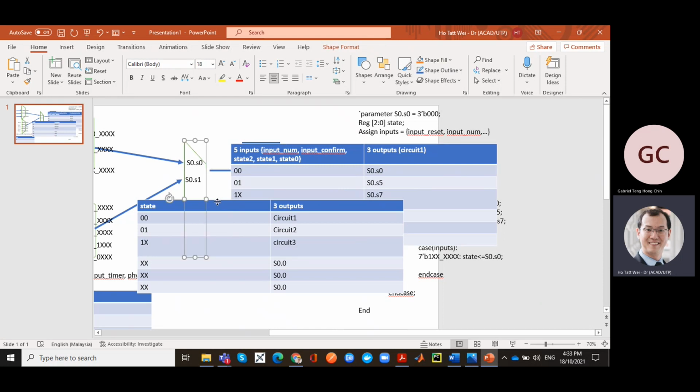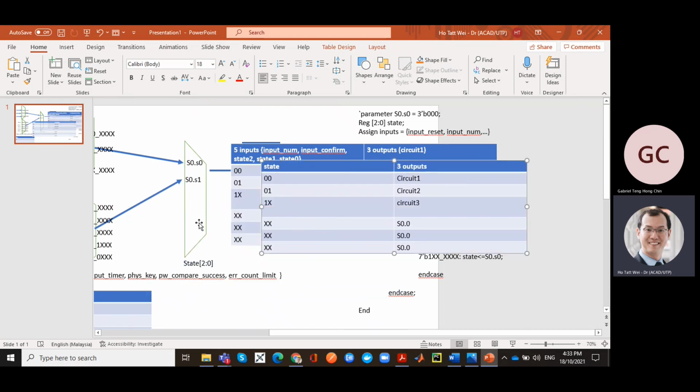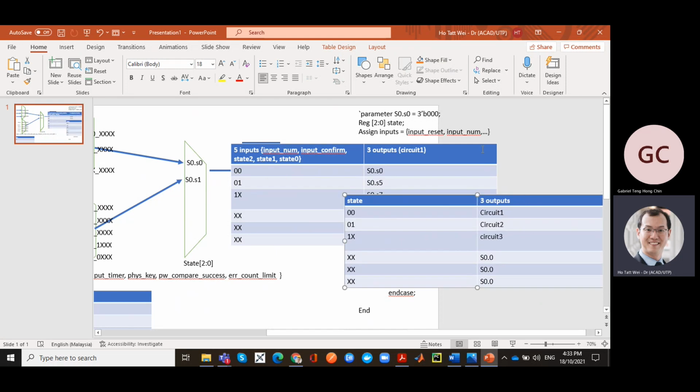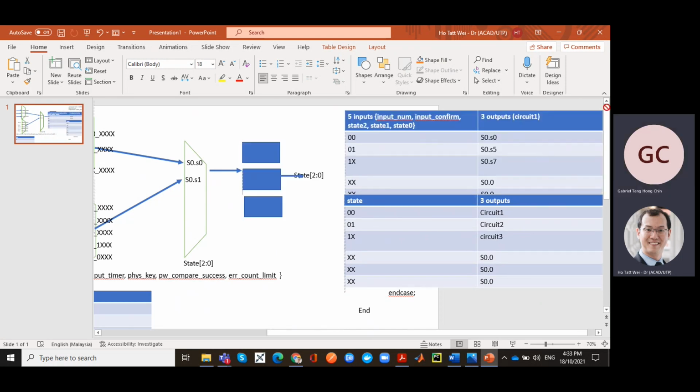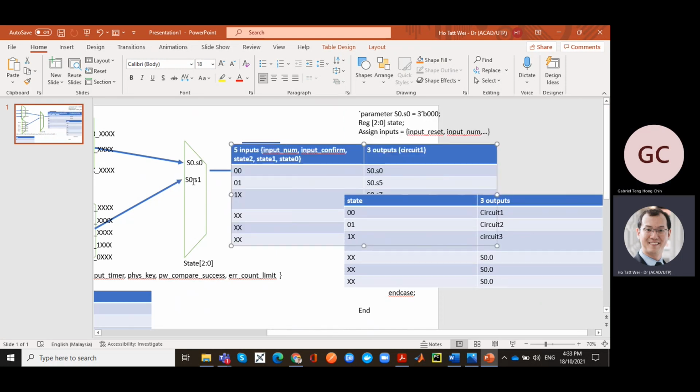That's it. The only situation here you have to watch out for is if you haven't figured out state 7. State 0 to state 7, you've got a perfect 8 states, so no problem. Can you see how this converts to a circuit, right? Because I'm just using a multiplexer here. But again, you've got permutations. If you want to combine these two, then you can reduce the number of bits here. There are many ways to implement this.